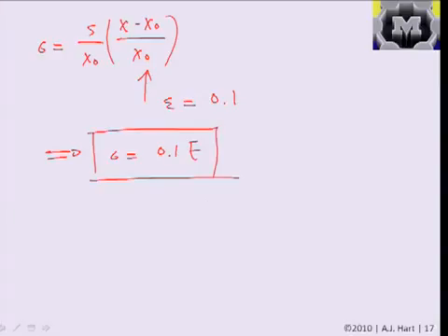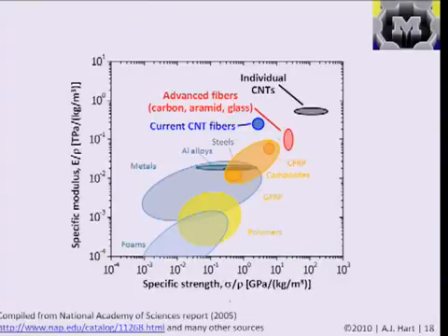And if we look at the real world of materials, very few things are close to this limit. It's more typical that materials will fail at 1/10,000th to, say, 1% of the Young's modulus. And that relates to how the materials are organized and how defects propagate through them.